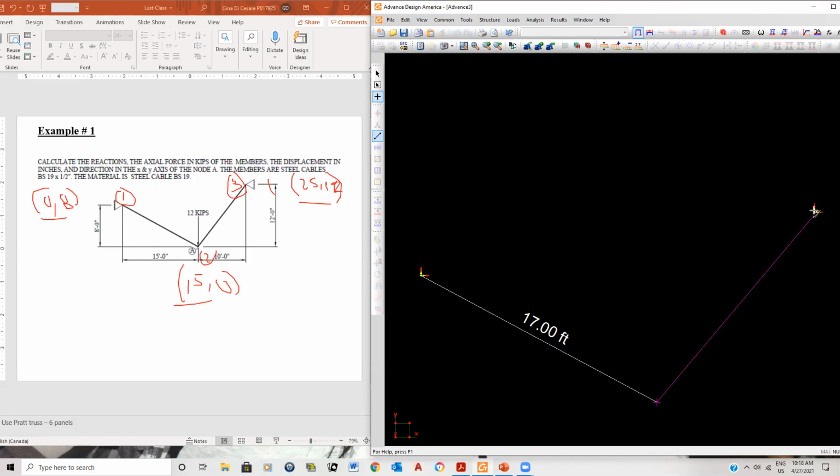So when I look at my results, I know where the program is starting to give me the information. 10, 12, I just want to check something. 10 squared plus 12 squared equals, square root equals 15.62. Good. I just checked to make sure the program works correctly. I use the Pythagoras theorem to calculate the length of that member. And of course, that should be 17.4.